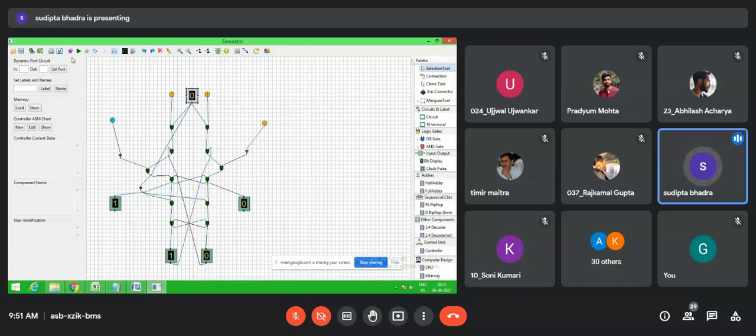We do not need to do this gate by gate simulation to resolve unknown, or click on this do case analysis, because as we are using the inverted clear and inverted preset, the improper initialization situation does not arise. Improper initialization means that lots of unknown is there. Bit displays are showing X because of the unknown.